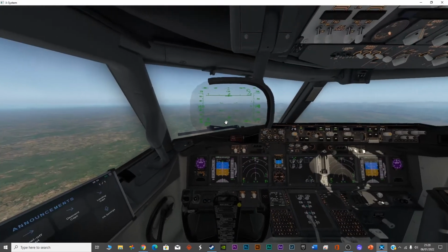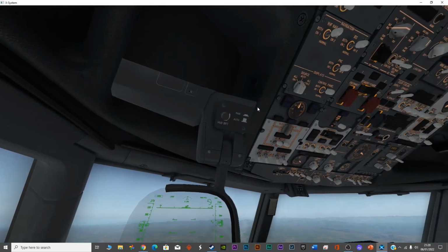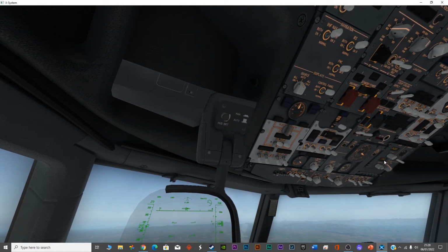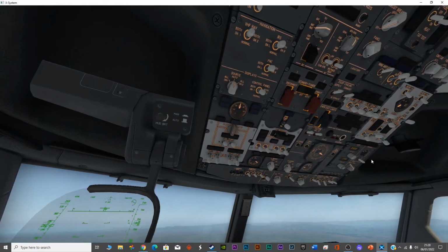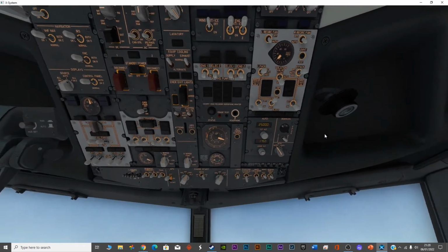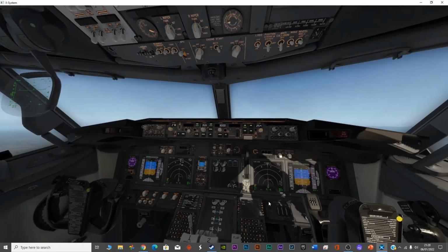Yesterday when the cabin pressure dropped and my pilot fainted, I was concerned. So then I just searched over the internet, and I just found out that it is really important to set the altitude over here and over here in these two options for the cruising altitude and for the landing altitude. And plus you have to set this selector, the cabin pressurization selector, to auto.